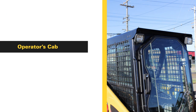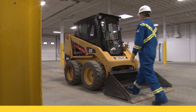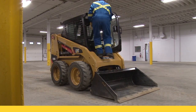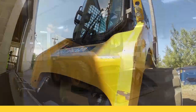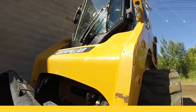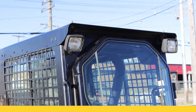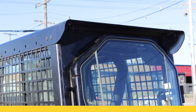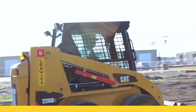Operator's cab. As standard safety equipment, all skid steer loaders have an operator's cab that serves as a rollover protective structure, or ROPS, and falling object protective structure, or FOPS. Because the operator's cab is there to protect you, it's important that you never modify the cab by welding, grinding, drilling holes, or adding attachments unless the modifications are engineered. Changes to the cab can take away from its integrity and affect its ability to protect you.